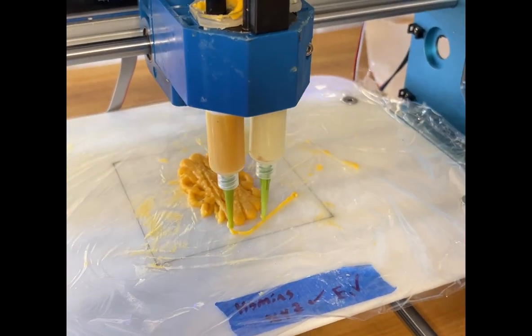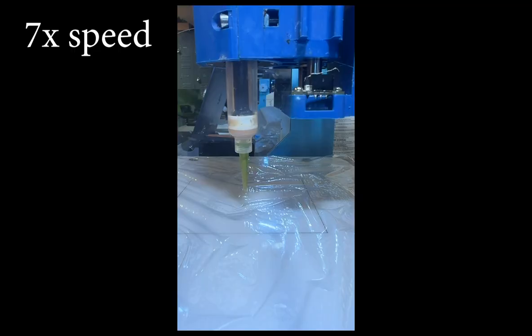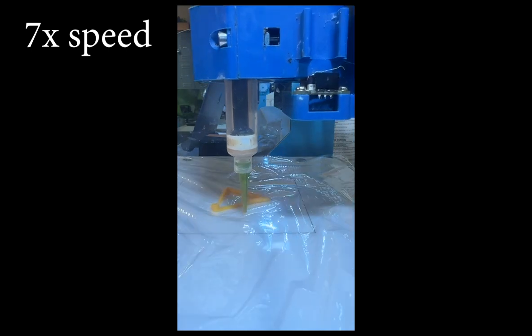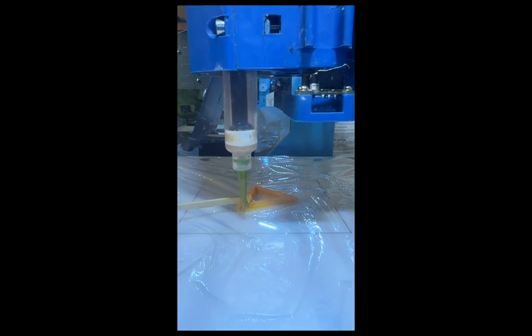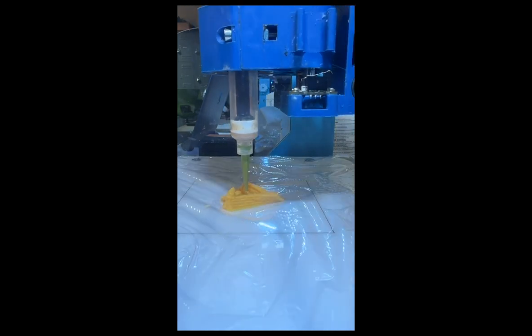For putting the material into the syringe, try and avoid having bubbles at all costs as they ruin the amount of material that comes out. When you first begin to start printing, make sure you add a bit of a delay into your code so that pressure builds up in the syringe and that it comes out evenly right as it touches the paper.